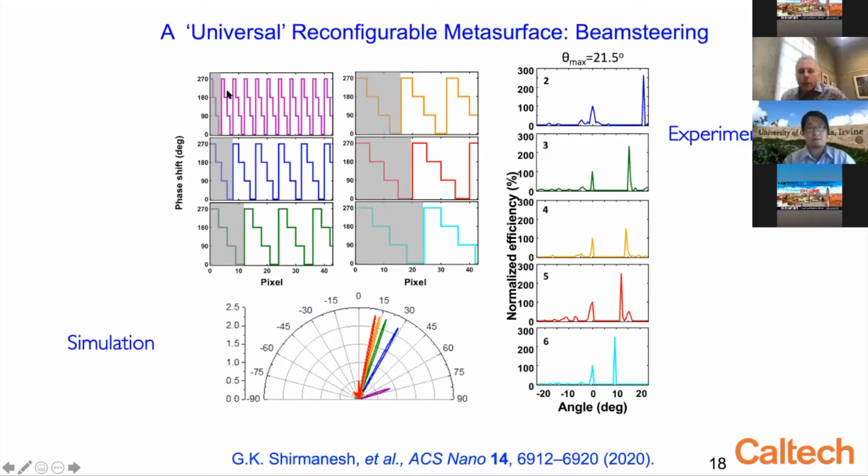So I can now adjust the slope of that phase gradient by changing the number of antennas that have identical phase levels in this 4-level phase scheme. And if I had perfect devices where I had no covariation of phase and amplitude, I would get highly directive beams coming out at these different angles corresponding to the different phase gradients depicted above.